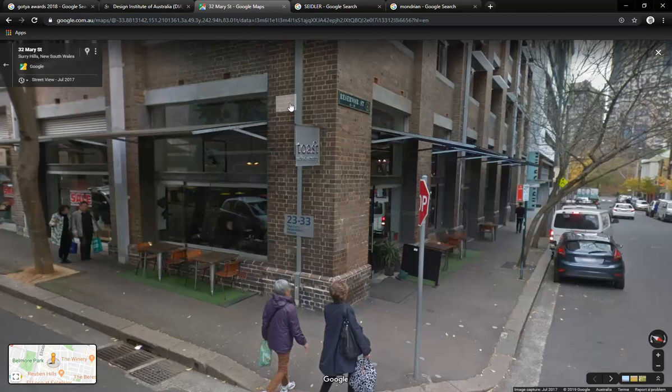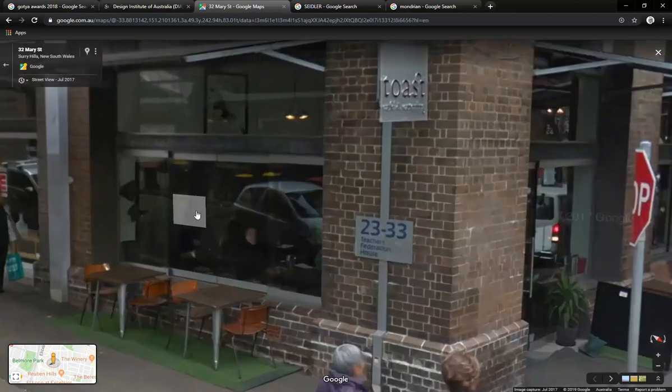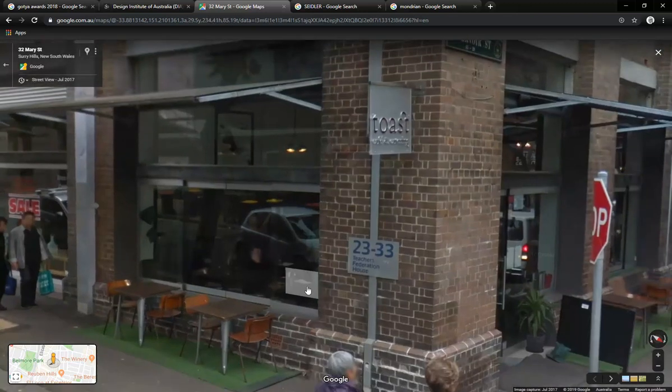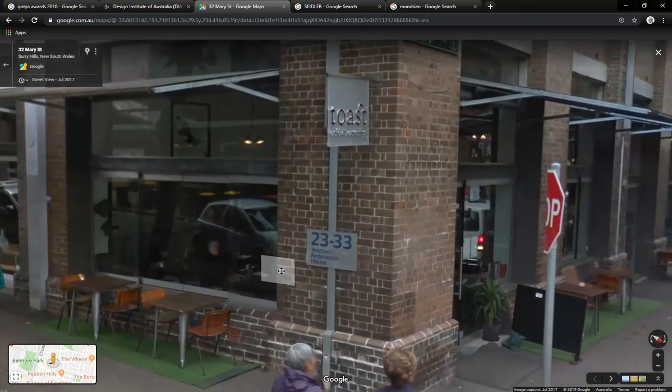And that's great. When you've got a building that's faced brickwork, this is what made me love brick. I never really liked the look of faced brickwork until I realised how useful it is when you've got a building that's made from it, because you can just count the bricks. So do you know the height of a brick? I know you do, because Kylie's been telling me. 76. 76 and then 10 mil for the mortar. There we go, that's right. So remember that measurement, and you can use that, if you count these bricks, to work out the height of anything like this. So you just sit there and go 1, 2, 3, 4, and you count those bricks.